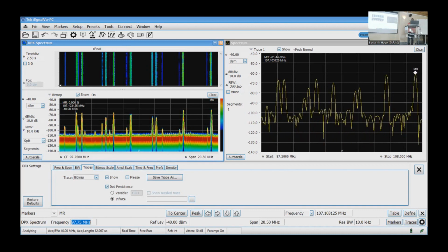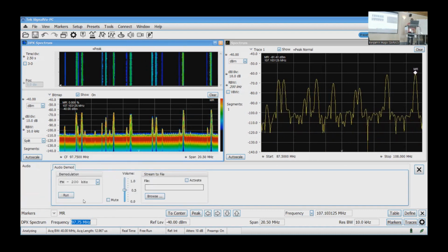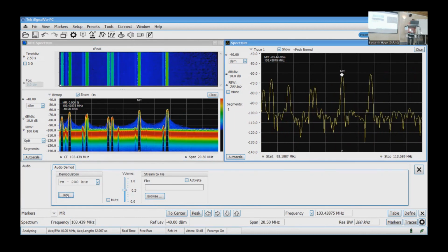So if we go to audio and FM demodulation, because we have to demodulate the signal. Remember, this takes the analog modulated signal, it goes through the receiver, and you have to demodulate the signal to get the information from the carrier wave, all right? What has happened is I've chosen my center frequency, but I need to align it with the frequency of the spectrum line, and I didn't do that. So let's try it again, but also there is interference from myself.